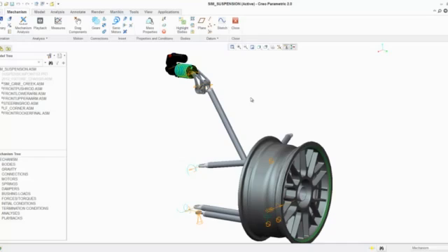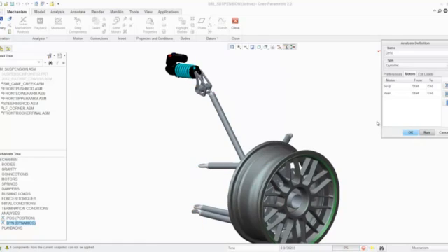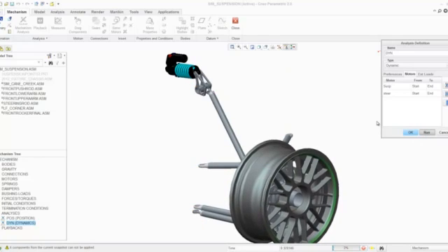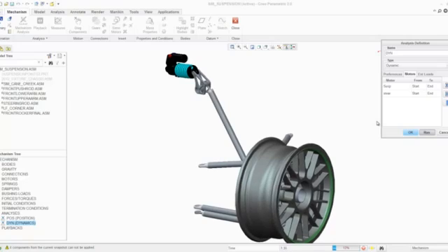And you can see that I've already, in the interest of time, predefined a number of assembly constraints. I've included a dampening spring up here and a number of servo motors that will actually go ahead and apply the forces to the model that we're looking to analyze. So just to show you that, let's go ahead and run that analysis by running those servo motors. And you can see here Creo Parametric is actually running through and calculating the forces that are at play.